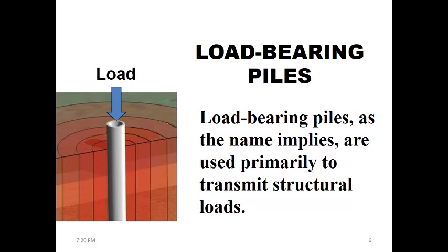Here we see a picture of a pile, which is a tubular pile, and the point of this discussion is to understand how these load-bearing piles work compared to sheet piles. The point of load-bearing piles is to support the vertical load and transfer it to the soil through its surface area, which is known as the skin of the pile, and the tip of the pile, the very bottom part that in ideal situations will reach the bedrock and transfer the load coming from the structure to the bedrock.